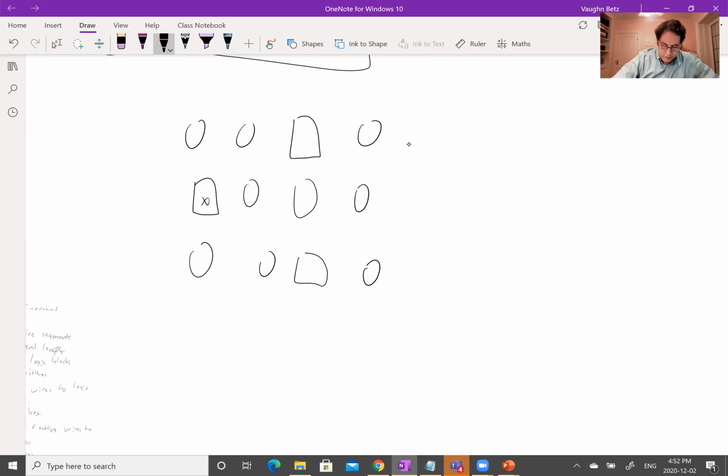And let's say I want it to go to a register that's in this logic block, and also a register that's in this logic block. So a conventional routing algorithm is going to just route this for minimum wiring and minimum delay. And it may balance, depending on how critical it thinks the signal is, how much it pays attention to delay versus wiring. So it might come out, for example, and take a wire here, connect to a switch, go down here, connect to another switch, go over here, and go into this block. Okay, and it would also go into this block. So from a wiring perspective, this is pretty good. And if this was a data path, it's pretty good for timing.